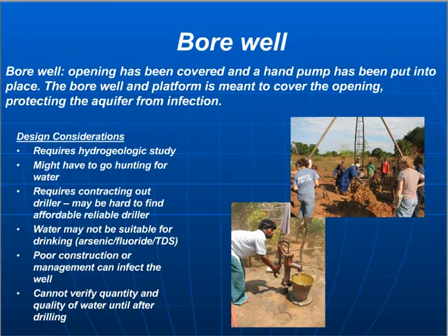And so there's a lot of design considerations for a borehole. For one, you need some sort of hydrogeologic study. But any kind of drilling method for a borehole is going to have some cost to it, and sometimes that cost is such that you really need to understand if there's a good chance you're going to get enough clean water out of it to make the investment worthwhile. So you need some sort of hydrogeologic study.